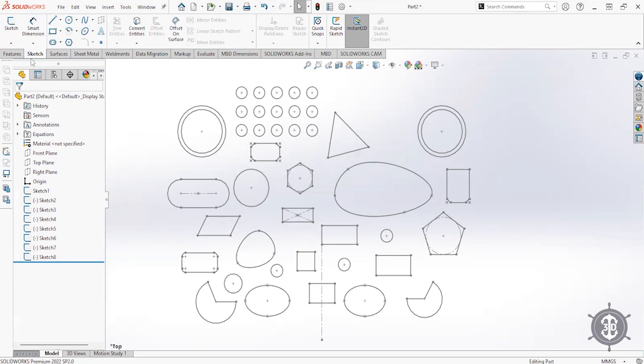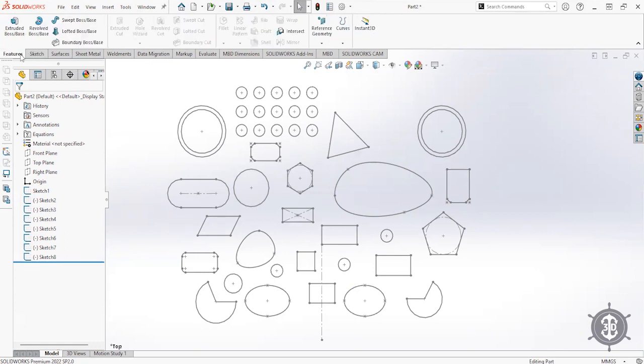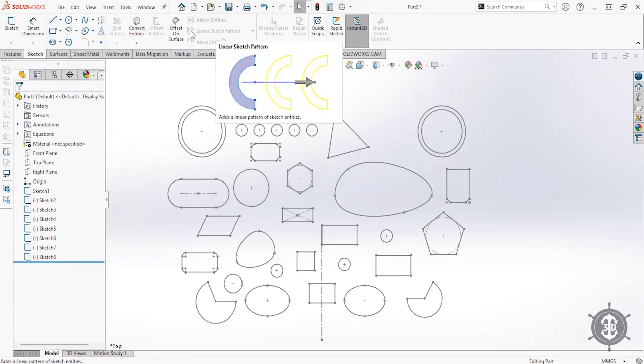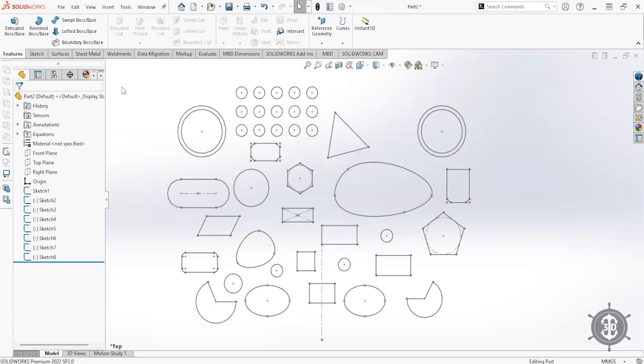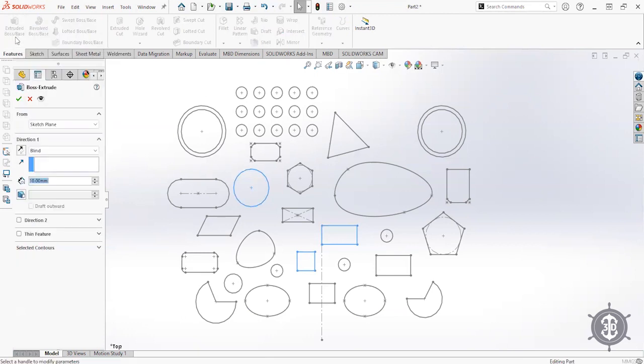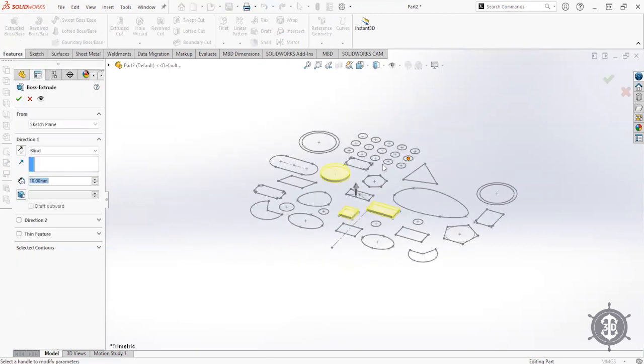Now, moving on to 3D modeling. So sketching is basically for 2D sketching. Now we'll change the tab to features. Features is basically 3D modeling. Now let's suppose starting with sketch 1. This is sketch. Now I want to convert this into 3D. How about starting with extrude? Okay. Now I can pull it from here or maybe entering a precise size, 250.